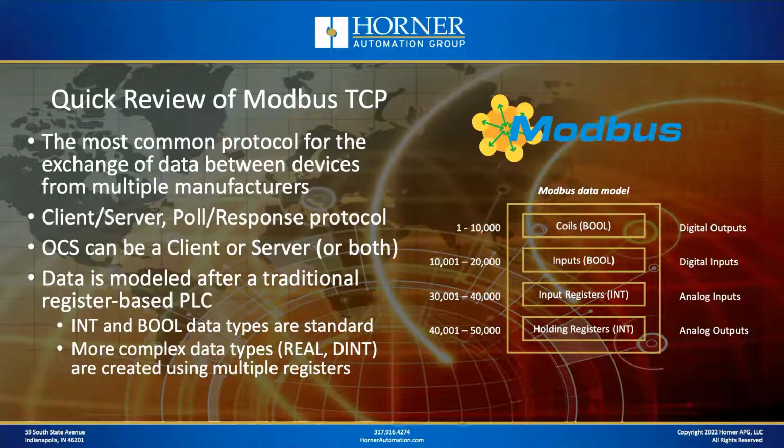Now, in Modbus, whether you're talking standard Modbus or Modbus over Ethernet or Modbus TCP, data is modeled after a traditional register-based PLC. The only native data types are integer and Boolean. However, everybody has implemented other more complex data types like reals and double integers simply by concatenating multiple integer type registers together. And on the right there, we have a diagram showing the Modbus data model.